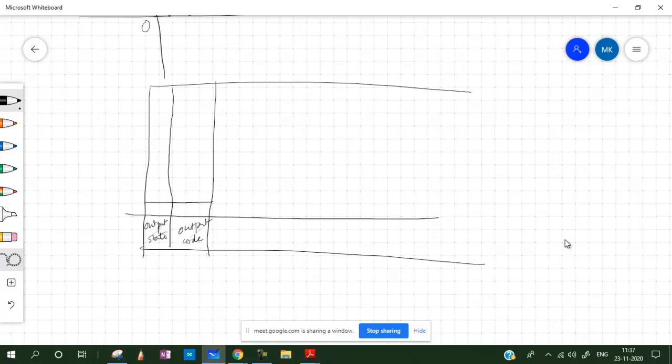So we have some digital values like 0, 0, 0. This means 3-bit, so we have a 3-bit A to D converter, analog to digital converter, or you can say a quantizer. So we have 0, 0, 1 that we have seen in digital electronics. Then 0, 1, 0. This is how the binary systems move. So 0, 1, 1, then 1, 0, 0, then 1, 0, 1, 1, 1, 0, then 1, 1, 1.